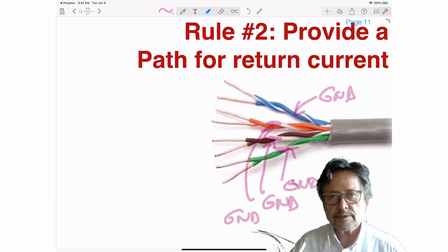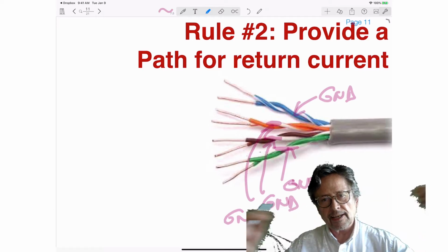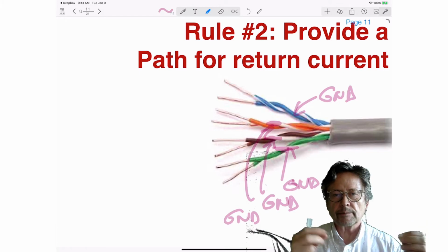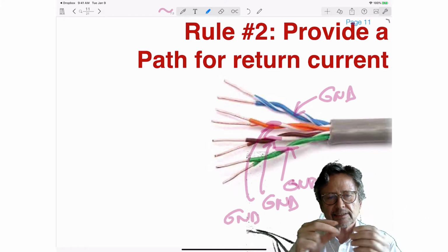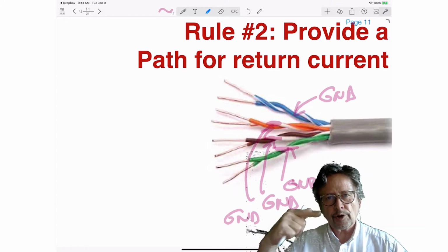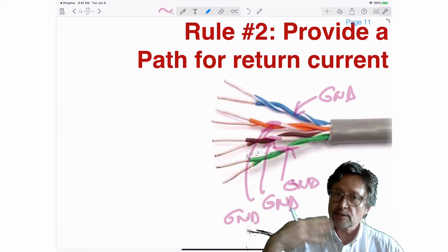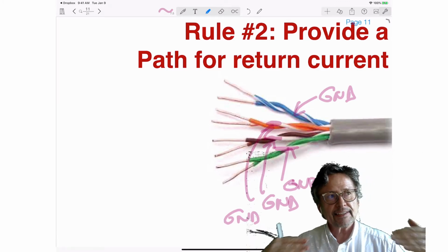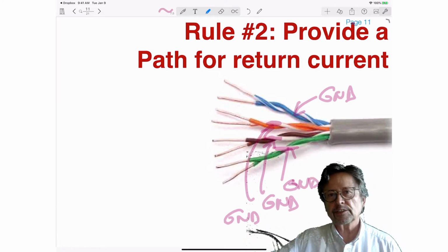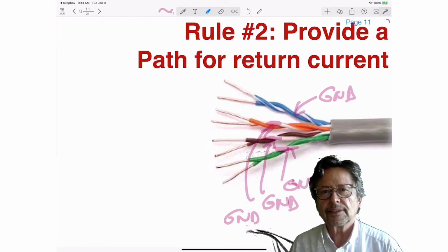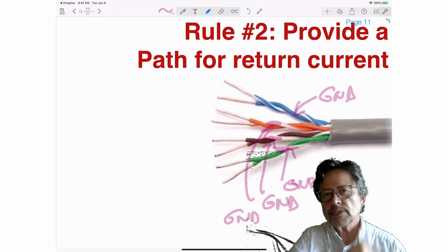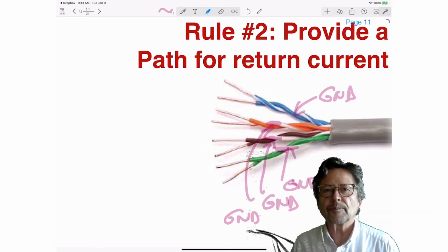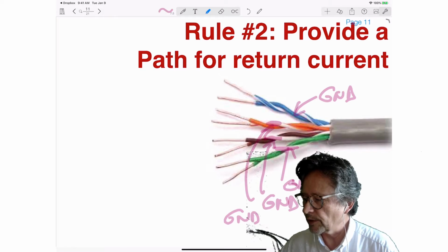These ground wires going around an electrical wire are going to create some kind of shield, because a rule of electromagnetics is that if you have a wire and a current that is oscillating fairly fast, and these bits go very, very fast at megahertz typical rate, then the wire acts as an antenna, and it's going to create magnetic noise all around us. So having these twisted ground wires around limits the amount of antenna power that we create.